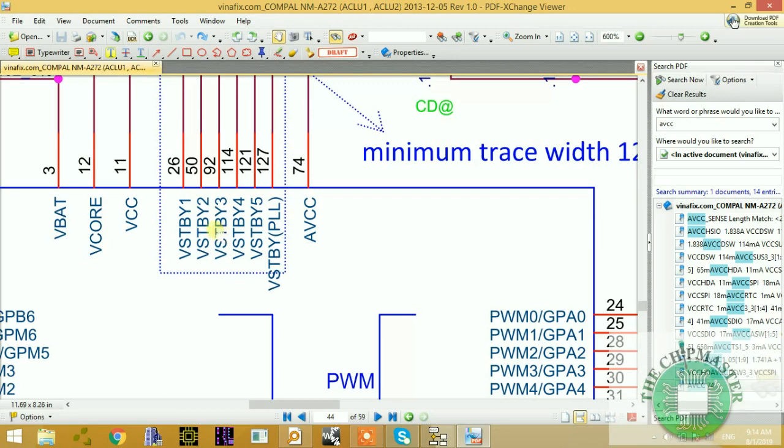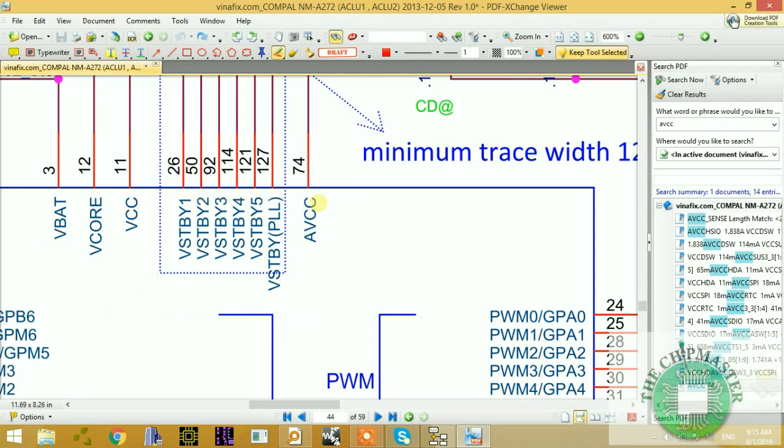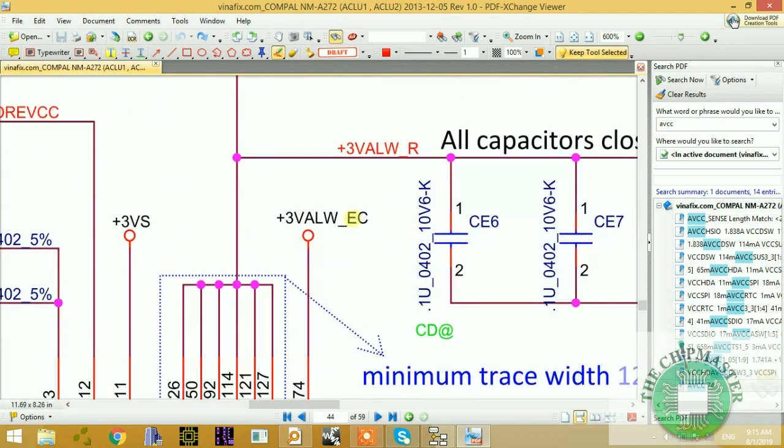So our focus is on these two supplies before we turn on, because if these voltages are not coming, then we can't power the laptop because we have no power, right? So these are your main critical voltages, very important voltages when working with the IO controller. So suppose this voltage is not coming. If this voltage is not coming, then we know that the board will be dead. We can't power. So we will have to trace where this voltage is coming from.